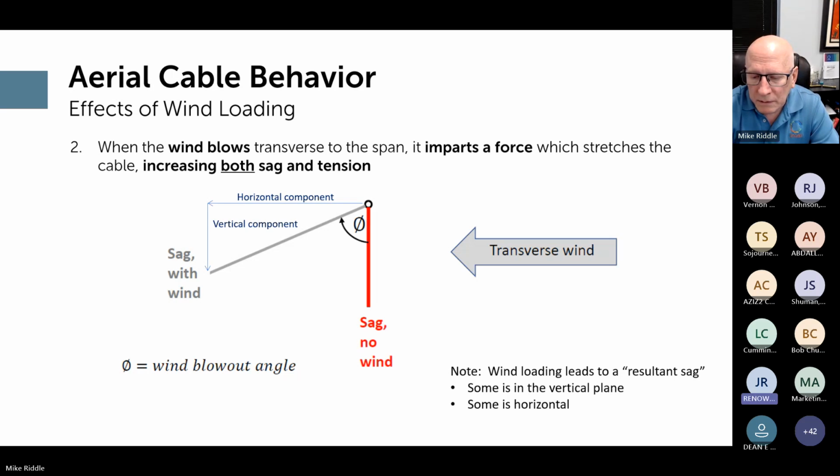Well, yeah, if the dynamometer is in series with the come-along hoist, that's a little bit better, because you can pull the conductor up to tension, and then you don't have to compensate for the length of the dynamometer coupling. However, what that dynamometer is reading is not the horizontal tension. It's reading the resultant tension at the structure, which may be close to horizontal tension.